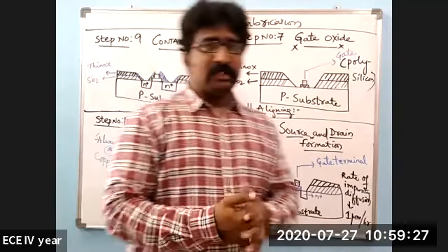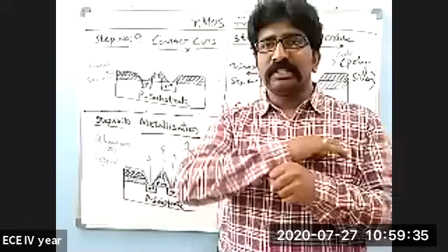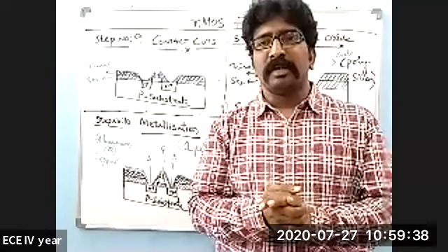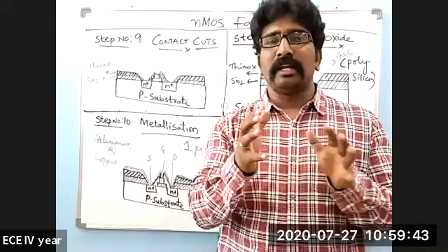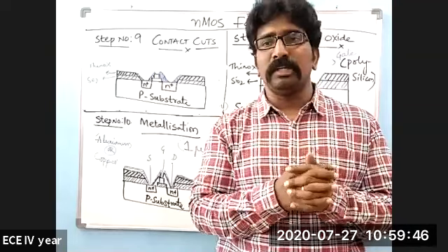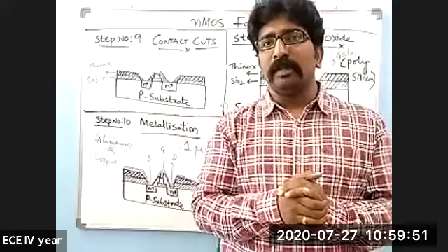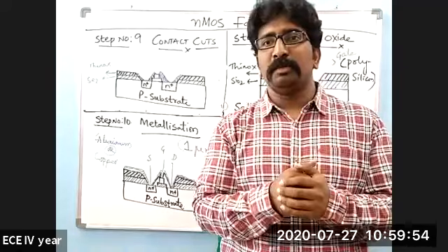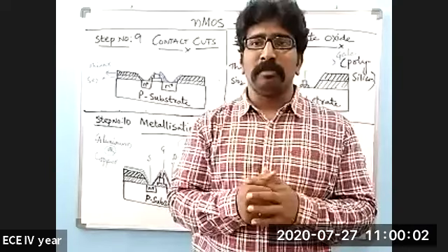Once the metallization has been completed, next will be the passivation method. Passivation is nothing else but covering this entire IC with some passivation materials which act as a barrier from the external world, so that any kind of harm should not take place to the integrated circuit, which can even degrade the functionality of a device. It can be any kind of device, PMOSFET or NMOSFET. So in this particular class we have studied about NMOS fabrication, where it has 10 basic steps.